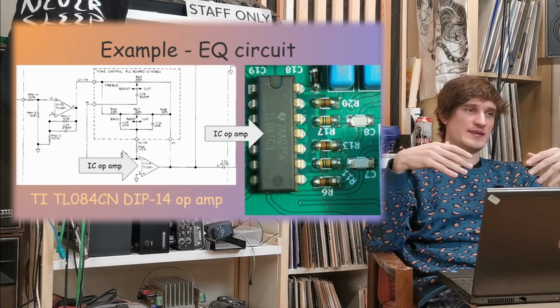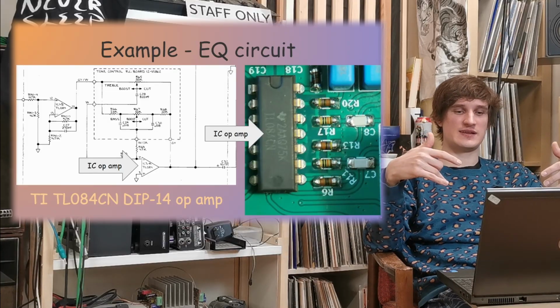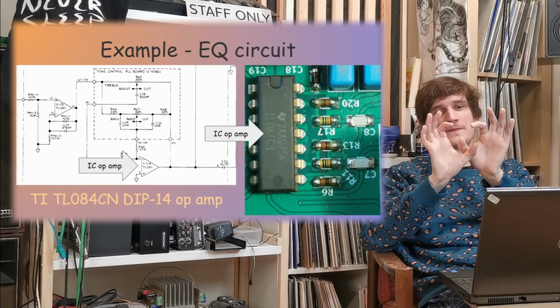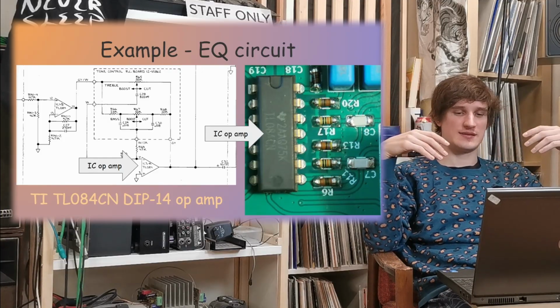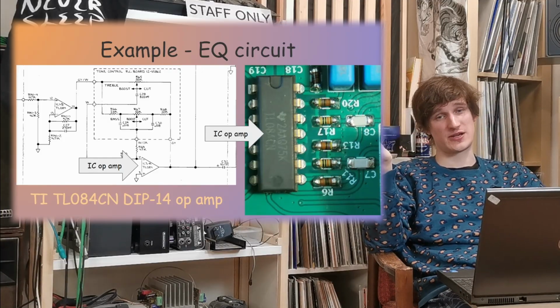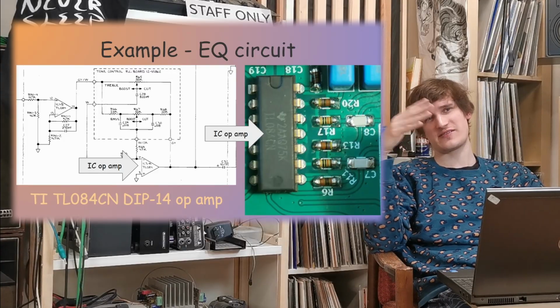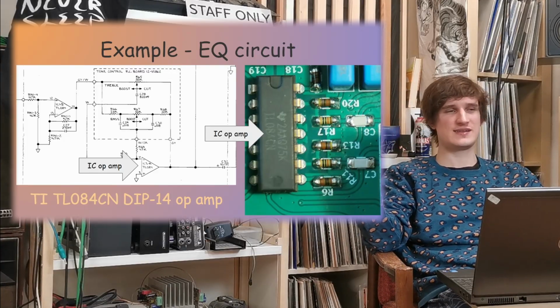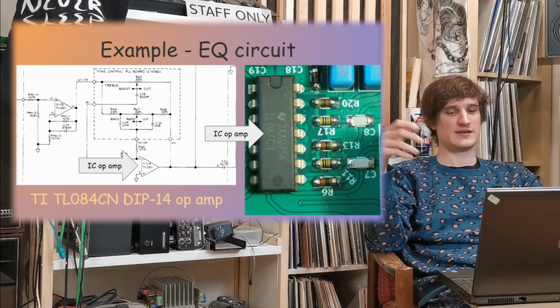So I paid the cost, because it takes more area on the PCB than an SMD part, and also it can introduce some parasitics. But the array design doesn't have high bandwidth; it's generally, let's call it, slow.